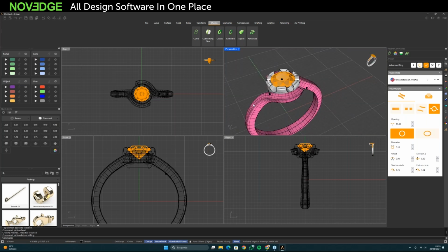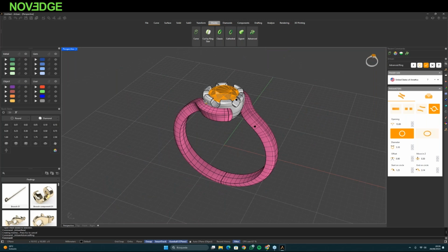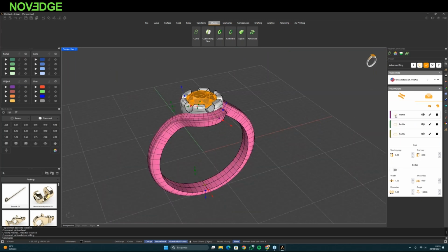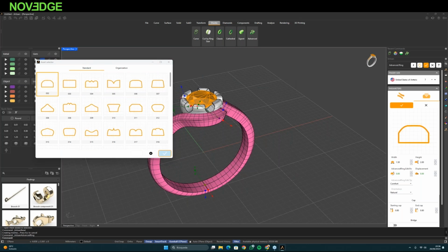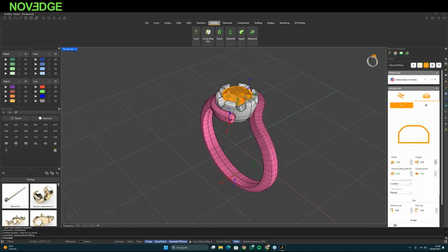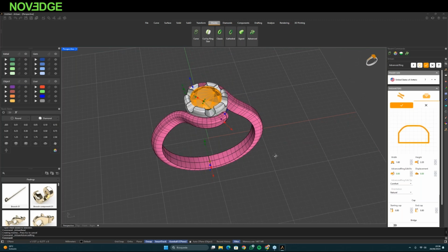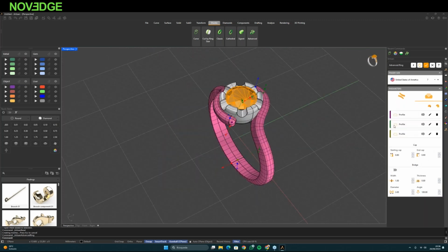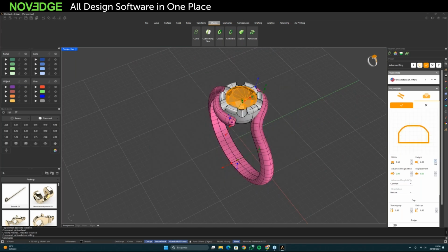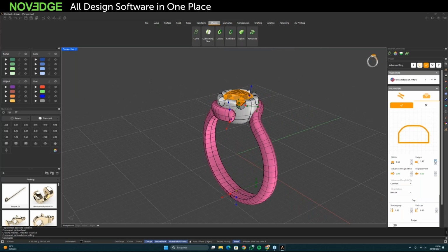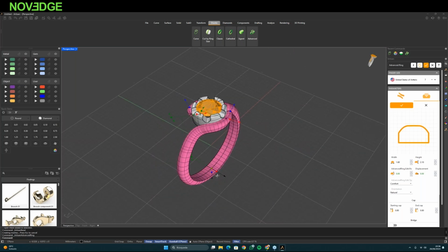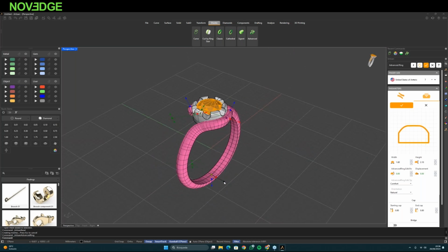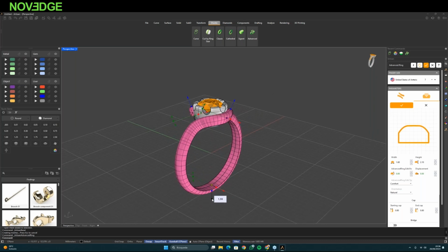And we can change also the sections of this sweep just by changing its profiles. So I'm going to use this curve for one of the ends, and I'm going to change its parameters. Just increase the head a little bit. Okay. Let's change the other one accordingly. Okay. And for the bottom section, I'm going to drag this arrow just also to modify the thickness and the width.